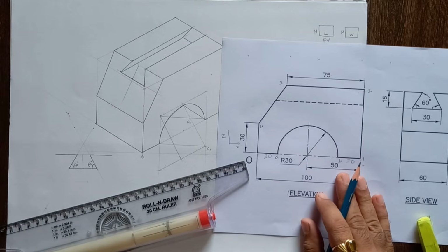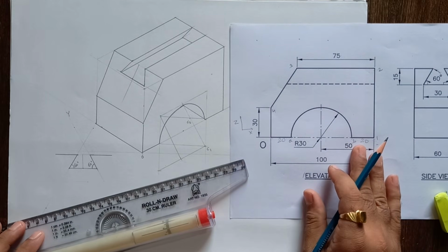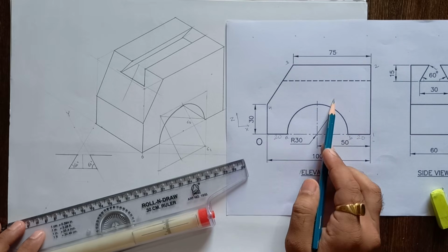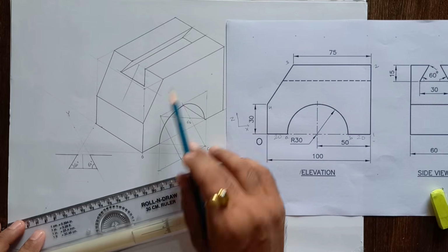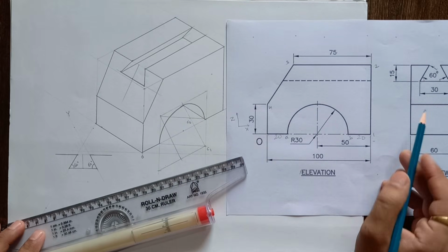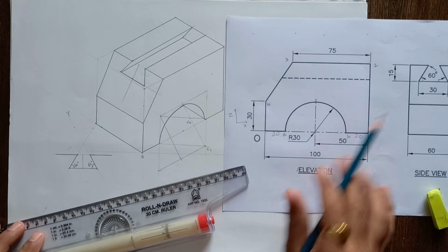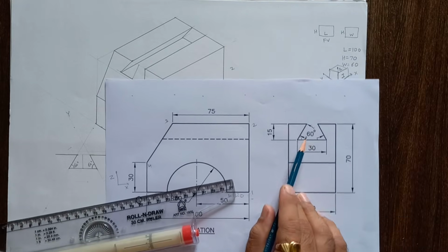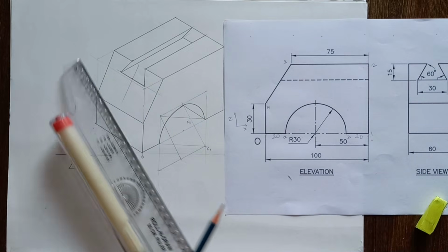You can see here, this is a complete solution. Dimensions are remaining, but you can see here. This is the object. This is the front, this is a front view. So this front view is correct, and in the side view, when the object is looked at from the left hand side, the observer can see the rectangular shape part as well as this profile. Okay. Now give the dimensions.